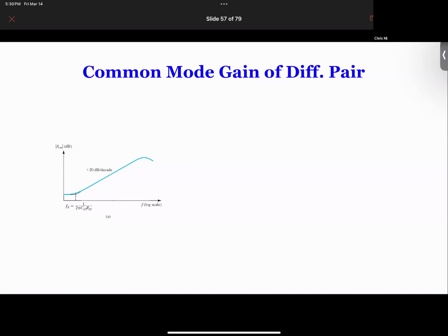That's not good, because the common mode is often something we don't want. It gets amplified. If that gets amplified and your small signal, AC signal, differential signal gets attenuated, that's troublesome, because the common mode rejection ratio becomes smaller, which is not good. You want the common mode rejection ratio as big as possible. So that's why you have this expression over here.